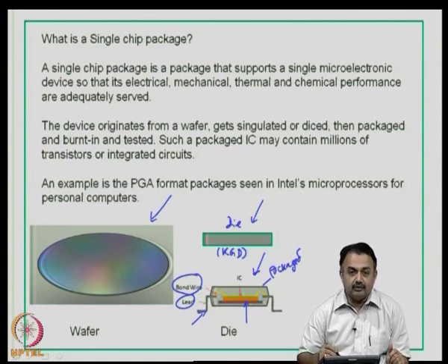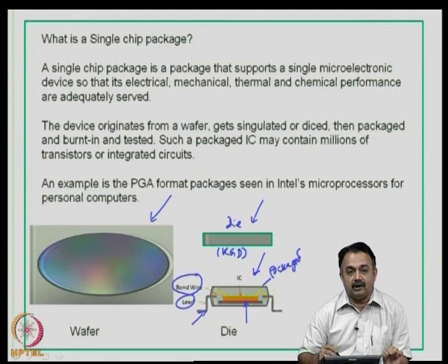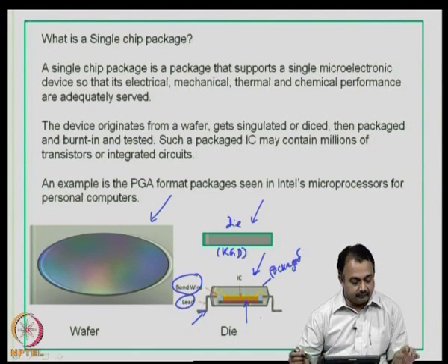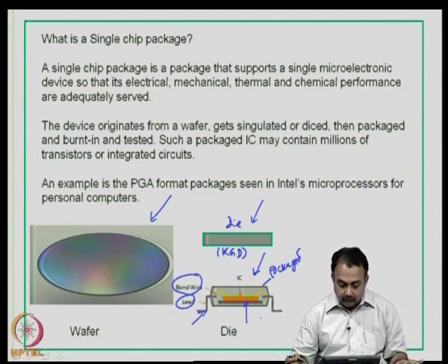So, you have to choose a suitable encapsulant and then mold the material, so that you get a well defined thickness of the plastic material, and as per quality you can check the thickness, the length of the lead frame and so on, and then send it into the market. So, wafer to single die to a packaged die.